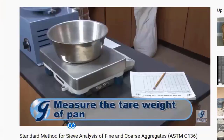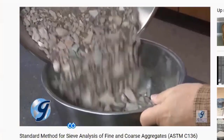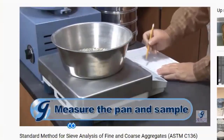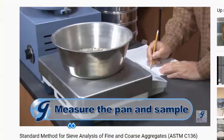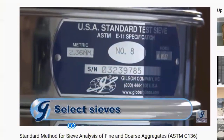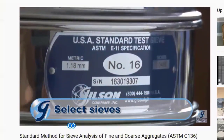Measure on a balance or scale the tare weight or unladen weight of your sample container or pan. Now place the test sample into the sample container and measure its gross weight. Next, select test sieves with suitable openings to furnish enough information required by the specifications covering the material being tested.